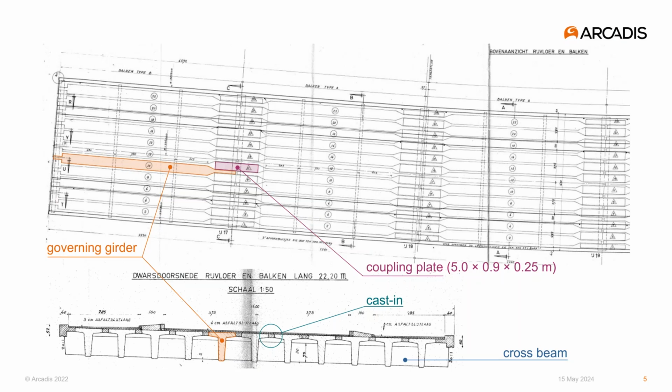The approaches consist of a number of sections, and each section is constructed as a continuous beam, composed of 5, 6, or 7 spans. The spans are made of prefabricated T-shaped pre-stressed girders, and initially these girders were positioned on temporary supports as isostatic independent girders, shown in orange here.